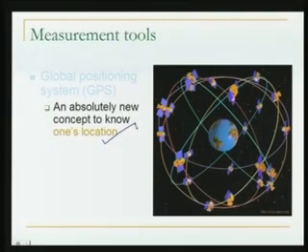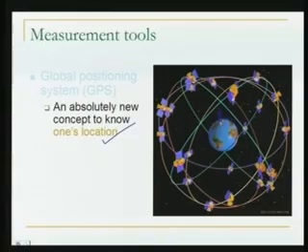What the GPS is? In the case of the GPS, as we can see here, all around our earth, we have around 24, I am saying 24 at the moment, though it's not exactly 24, it's more than that, number of GPS satellites. And these satellites are orbiting the earth in such a way that at any moment of time, if you are standing anywhere, you can see at least 4 satellites, of course more than that. You have a receiver. A receiver of the GPS may look like this, or maybe it will be a simple handheld device like the mobile phone.